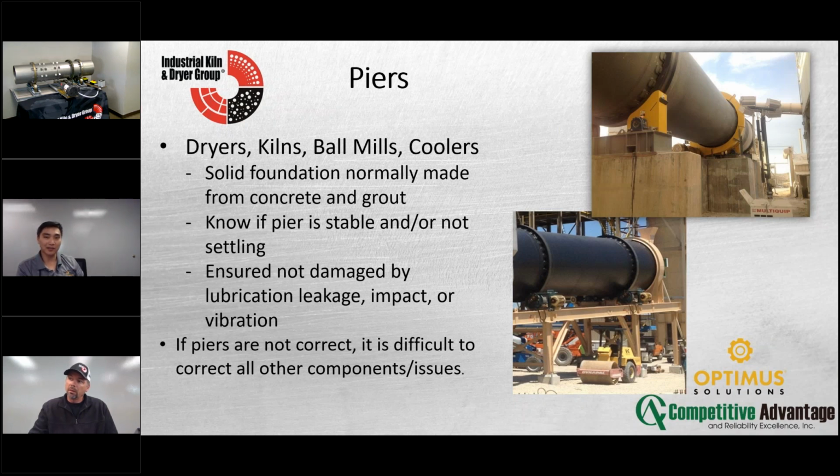It uses motion amplification. Ultimately, you have a high-speed camera, and then we amplify the pixels on it, and it can show you where the vibration is. The key there is looseness. Hey, if you tighten this bolt down a little bit, it'll help. We may think about doing one of the webinars showing that unit. It's a small segment.